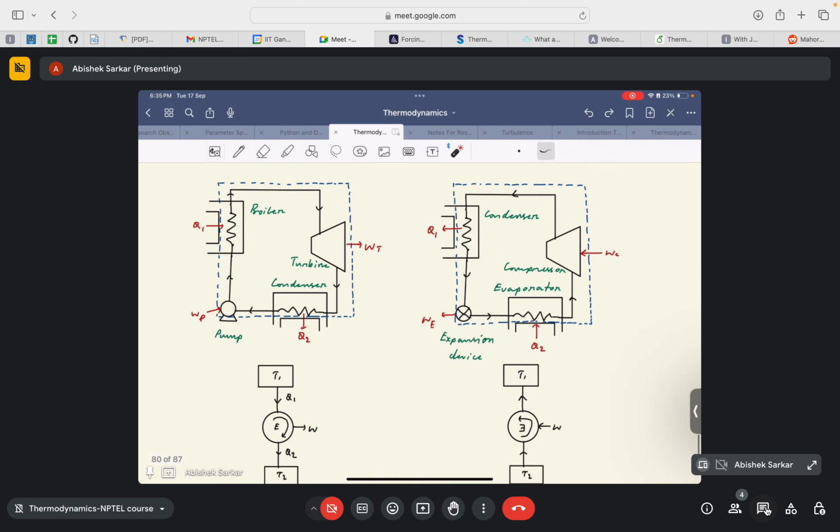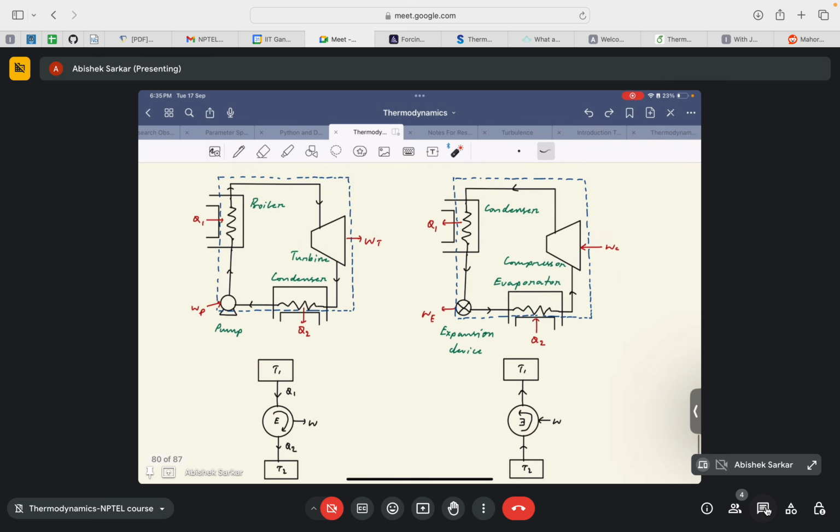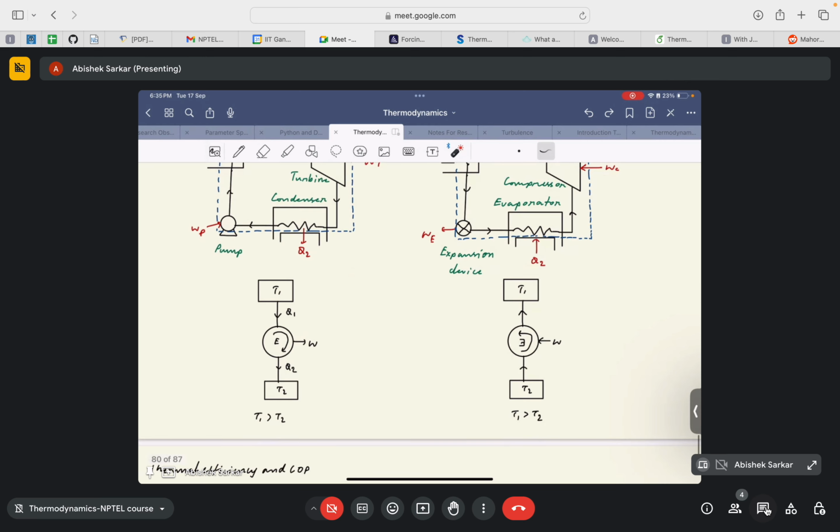Similar can be discussed about the heat pump, where this is our heat interaction of interest. Basically, in the case of a heat pump, heat is being absorbed from the colder surrounding and being pumped back into the room where we want to keep it hot. So this temperature will be higher than the ambient temperature within the room, so that the room can be heated up, and the additional heat that is used to heat up the room is being absorbed from the colder surrounding outside the room or the system. Okay, so that's the main difference.